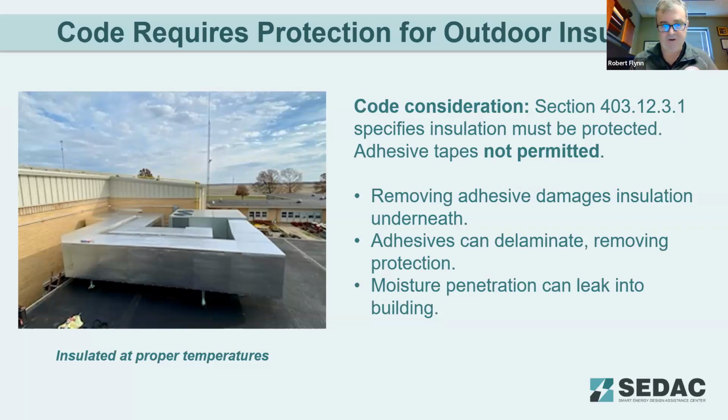I'm trying to think of the word. Ponding on top. Yeah, so it actually keeps the water from pooling on the top of the ductwork. So there should be a little bit of a pitch on top of that duct, but otherwise, it's a properly done job.